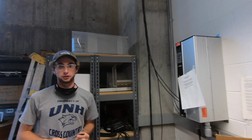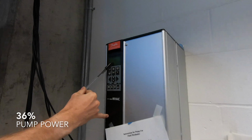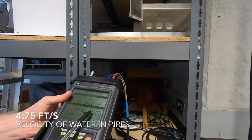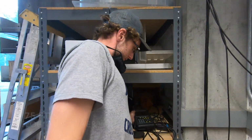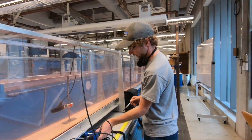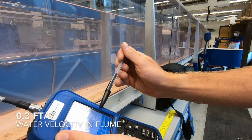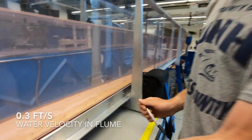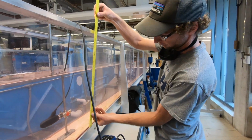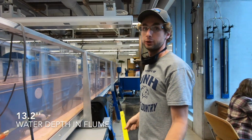Alright, we're now on trial 6 of part 1 of lab 3. The pump is running at 36% power. The water in the pipes is flowing at 4.75 feet per second. The Marsh-McBurney flow meter is currently reading 0.28 feet per second, or just jumped up. Call it 0.3 feet per second. It does fluctuate. At a depth of approximately 13.2 inches.